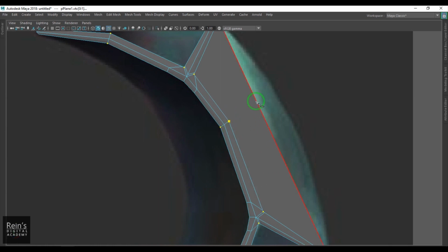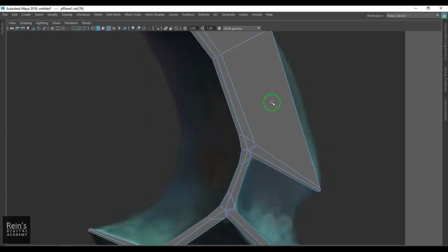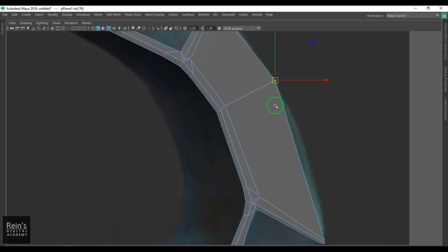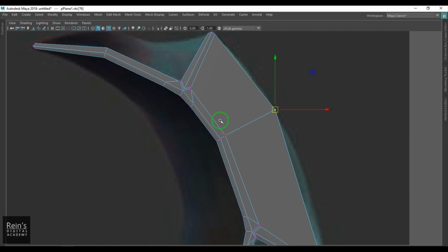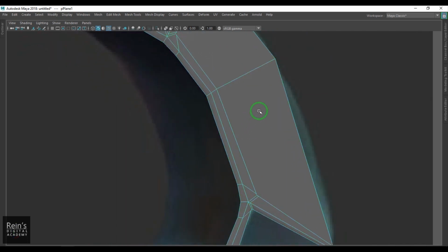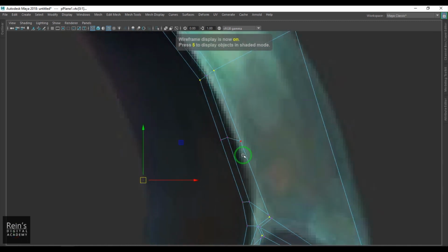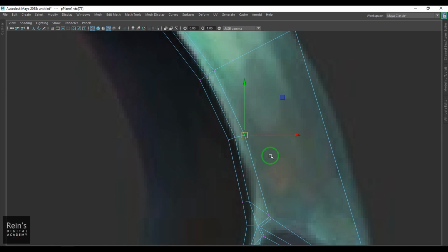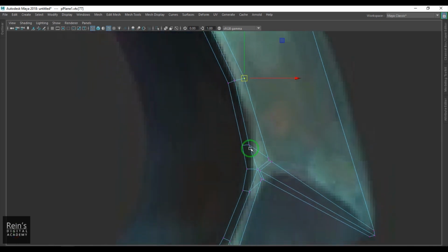So select that, connect there, and then you should be able to get that curvature. Okay, so it's very simple to get this. So I need to add lines here, so I'm using the multi-cut tool, and whenever you are adding lines, make sure that the lines are adjusted and respect that curvature, which is very important while you are